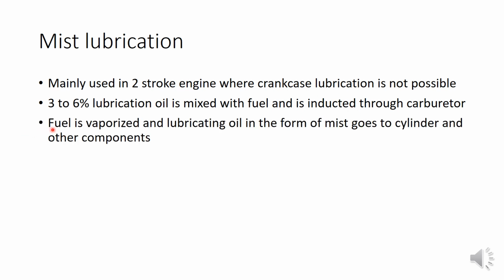And due to the high temperature inside the cylinder, the fuel will be vaporizing, and at the same time the lubrication oil will form as a mist. That is why it is known as mist lubrication. So this lubrication oil, due to the high temperature inside the engine cylinder, will form as a mist, and it will go to the cylinder and other components.